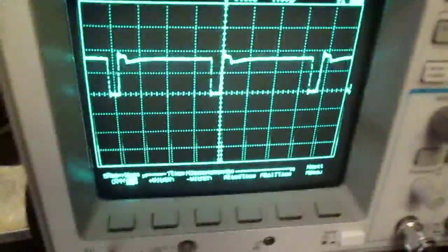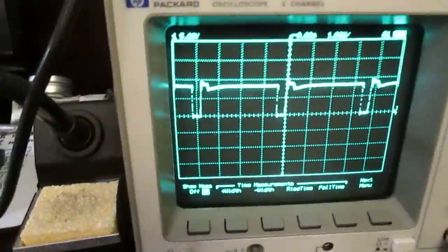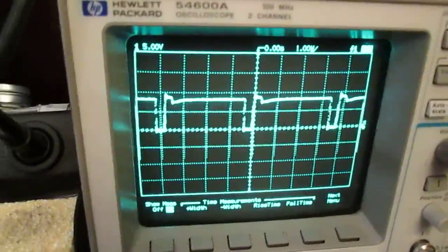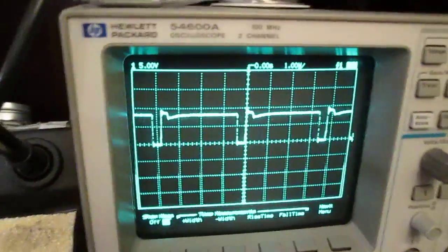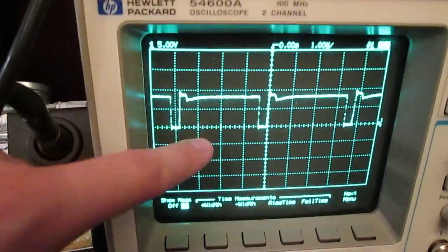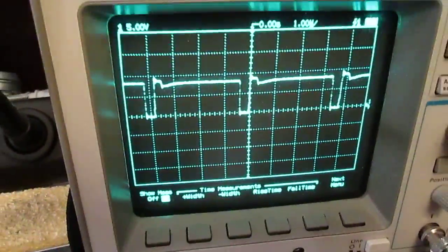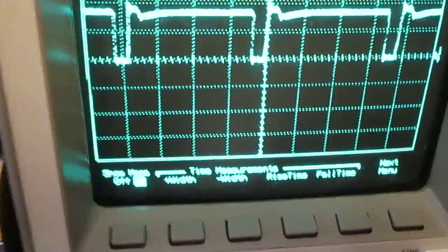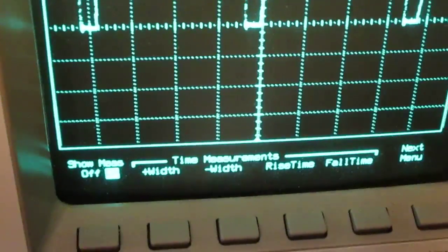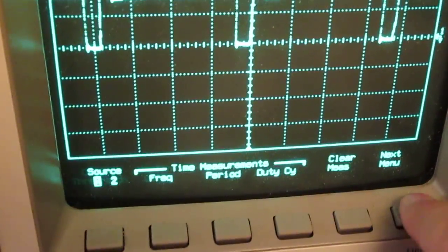So you have all these buttons, right? And you're like, wow, that's a lot. So it's really not that big of a deal. The things you're gonna wanna use mostly are like voltage peak to peak, meaning from the top to the bottom, that's peak to peak. So that shows you how big your signal is. I know it's hard for you to read what this is, so that's like time measurement. You can do different measurements, which is fantastic.